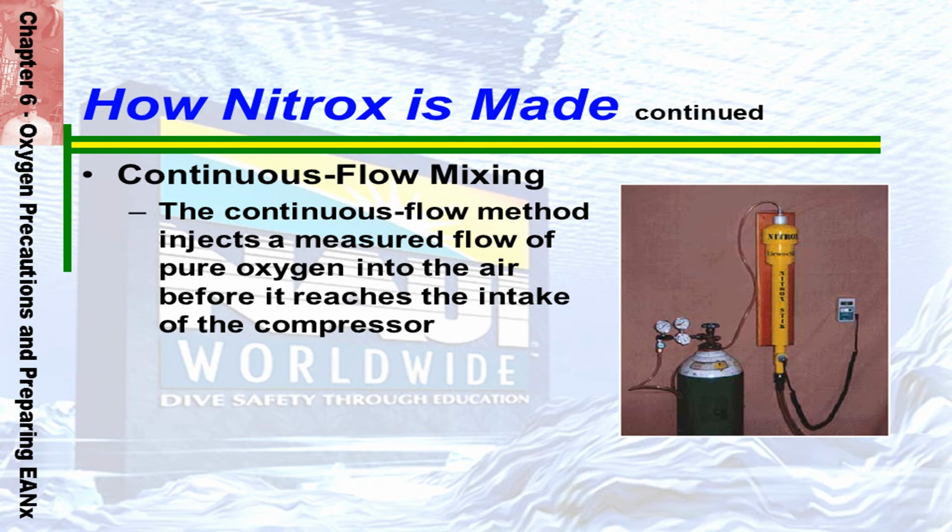As the high-pressure nitrox exits the compressor, the oxygen fraction is analyzed online, and the oxygen flow at the low-pressure intake is fine-tuned, either manually or by automatic feedback control, until the desired blend is attained. The high-pressure nitrox is routed to a bank of storage cylinders, from which it will be drawn to fill individual scuba cylinders.